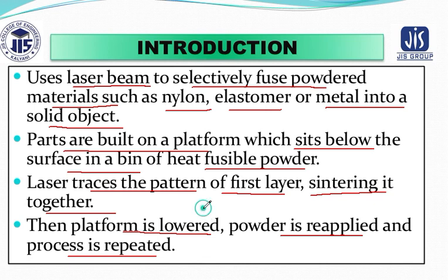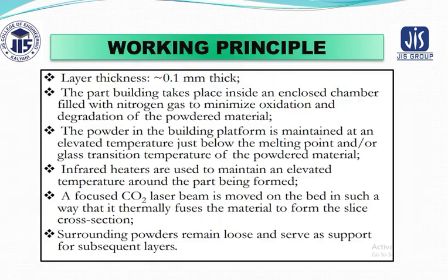Now let's look at the next slide. In the working principle, the layer thickness is about 0.1 millimeter. The part building takes place inside an enclosed chamber filled with nitrogen gas to minimize oxidation and degradation of the powder material.